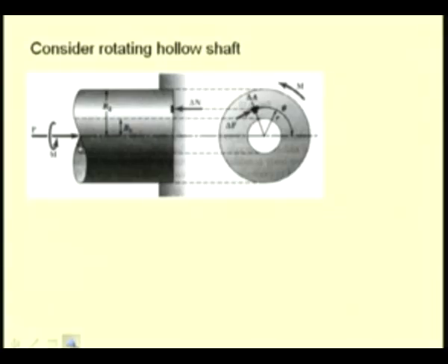So, let us consider a hollow shaft as shown in this picture. Let R2 be the outside radius and R1 the inside radius of this hollow shaft, which bears onto this support in this end face. There is an axial force P, and in order to overcome the friction in this end face, a moment M is applied in order to keep this shaft in the running condition.